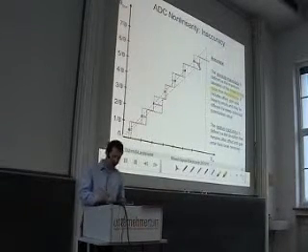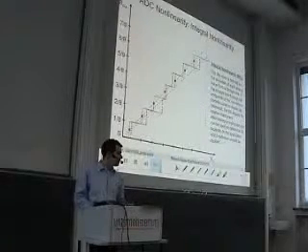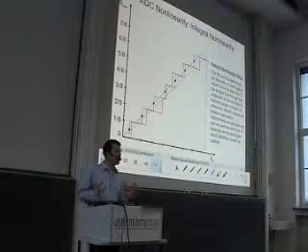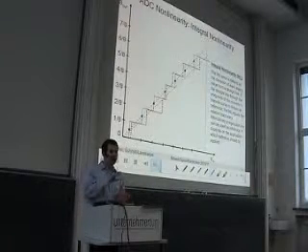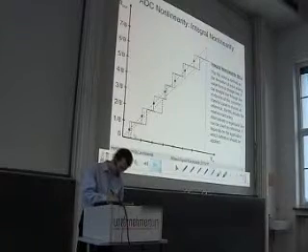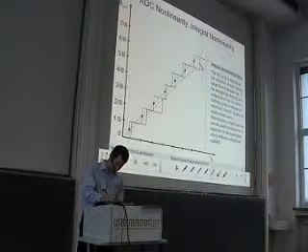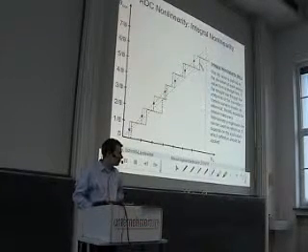Again, more often used is the integral nonlinearity, and for the integral nonlinearity we again need this reference line. We can choose either a reference line that connects the very first and the very last analog step. This is what we use here also.